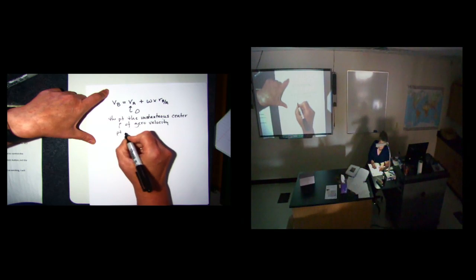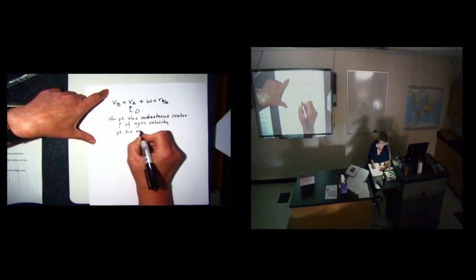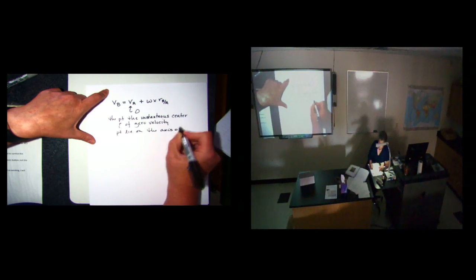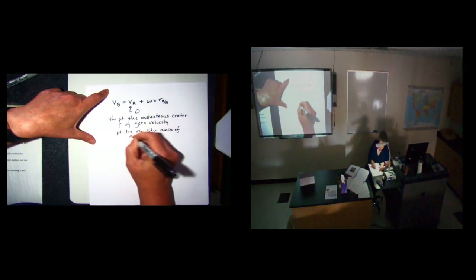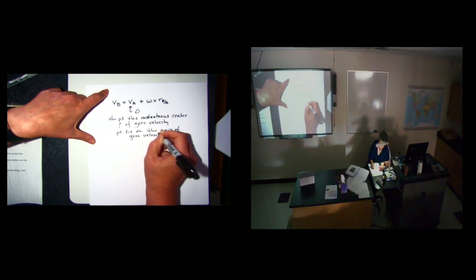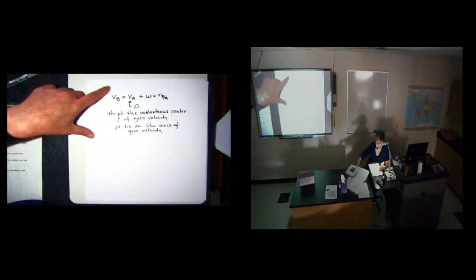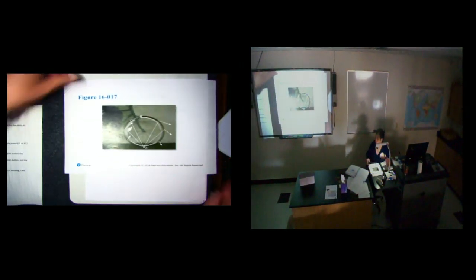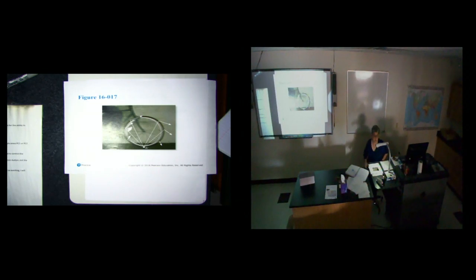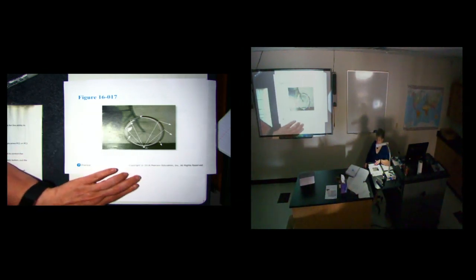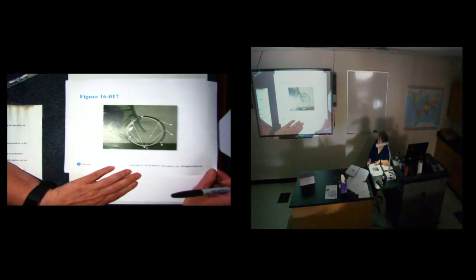I know this angular rotation and that velocity. If I know the velocity at A and I know its rotation, I can find this point where the velocity is equal to 0. I can do it again if I'm finding the location of the point where I know VA and VB, I can come back and find this point, the instantaneous center.